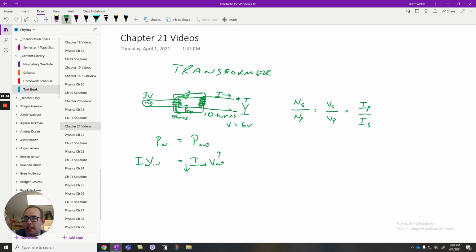So here's the basic idea. We have a power supply station. This is the dam power supply. It's going to produce something at, say, 1200 volts. But in order to save energy as I transfer the power, I need to step it up. So I'm going to go through a transformer that's going to step it up. And it's going to bump it up to something like 240,000 volts, much higher voltage.